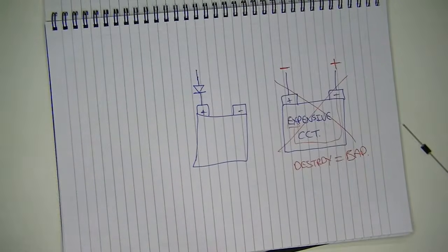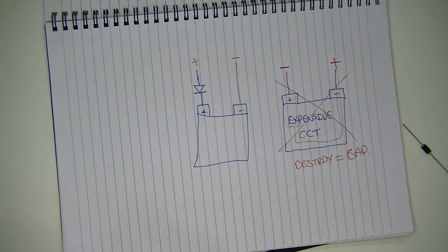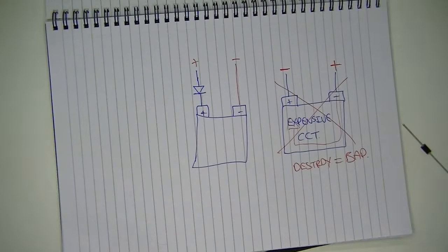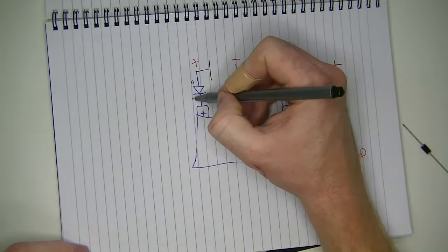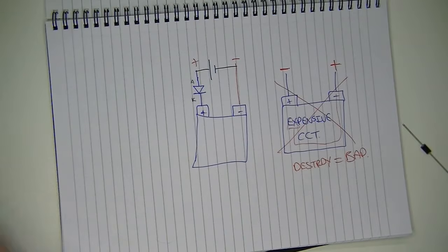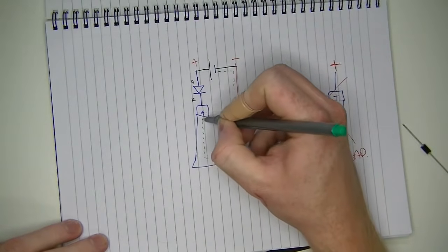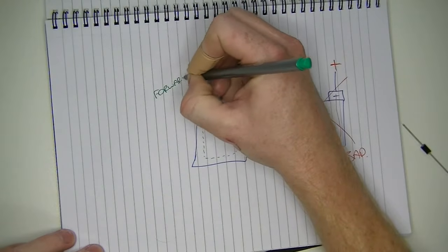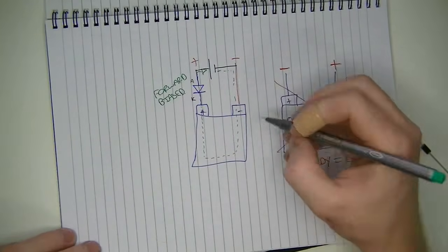So now this forms my positive input, and this still just remains my negative. So just like we had previously, as long as we connect the power supply up correctly, that is positive to the positive, so there's the anode, cathode, negative to the negative, we're going to get current flow through the thing. So current will flow from negative through the circuit, do its thing in there, through the diode to positive. So the diode here is forward biased, which means it's turned on and it's allowing current to flow in the circuit. So that is all good.